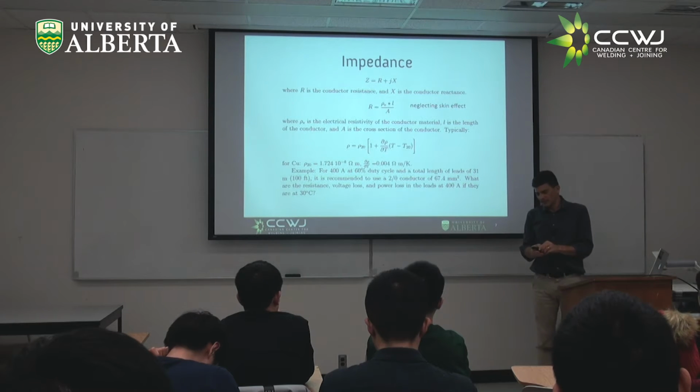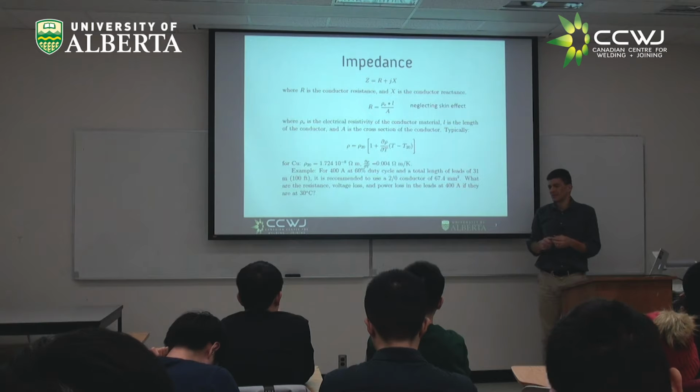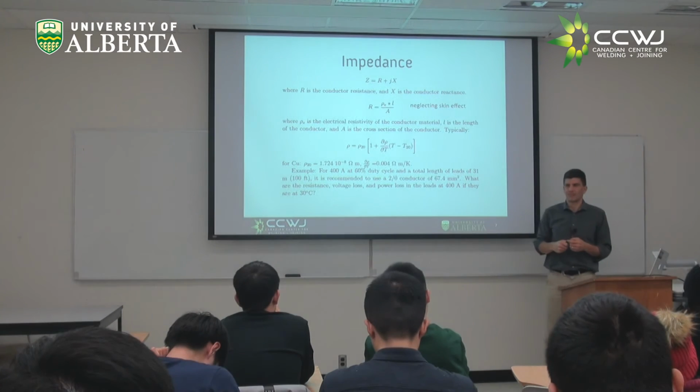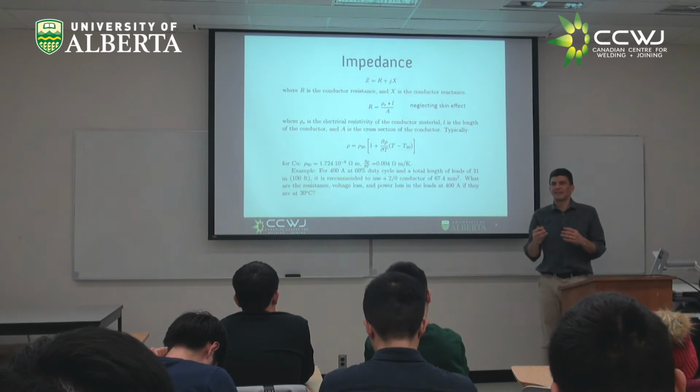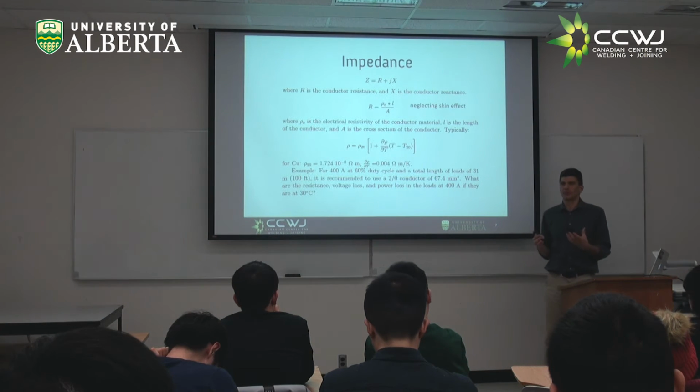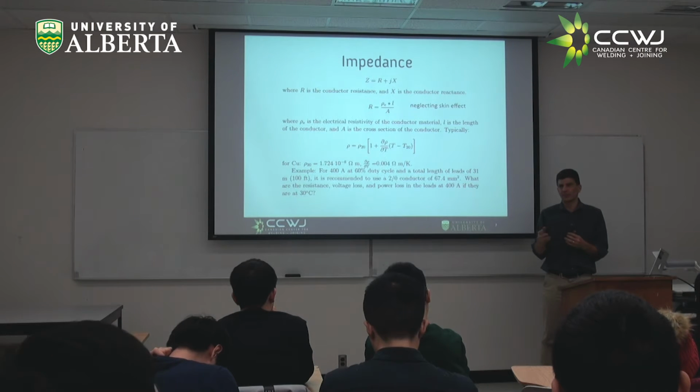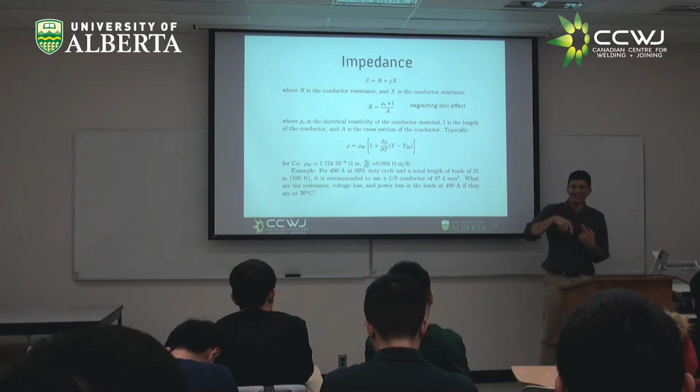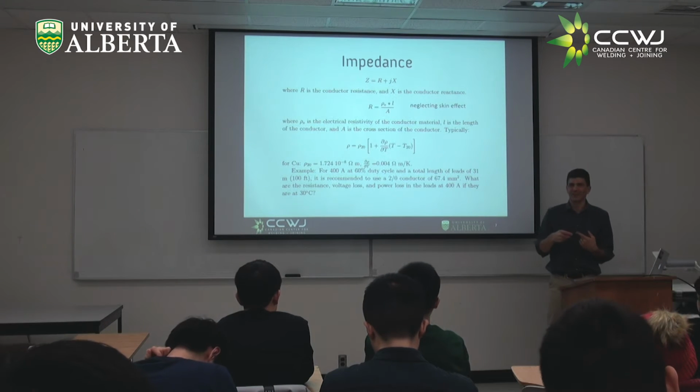If they use very big leads, do you think they can use good waveforms? No. And it's all consistent. Do you remember what they would use to make buildings? What process they typically use? Either stick or flux core, but they don't use processes like MIG with gas. Neither stick nor flux core typically use pulsing or waveforms. It's all consistent, right? You see how the whole thing, why things are what they are.